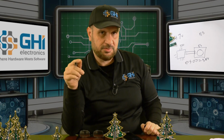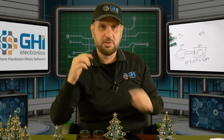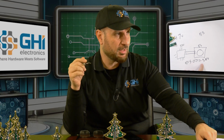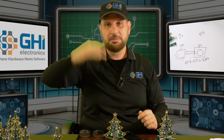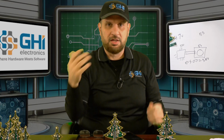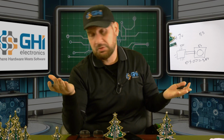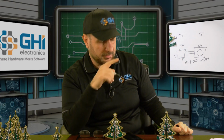If these LEDs expect a high level to be at 3.5 volts, of course it's not going to work. The chip is at 3.3 volts. Where would the 3.5 come from? So the LED would never see the pin going high. The pin is going high up to 3.3 volts but the LED would not see it going high because it expects 3.5 volts. So that could be it. But why 4.7? Why did 4.7 work?